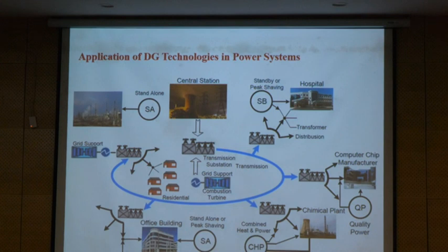Sometimes reactive loads change the voltage stability of the system, but we can increase the injection of reactive power from DG sources to the grid, and then we regulate the voltage. And in some cases, when we have more active power, it's like this.